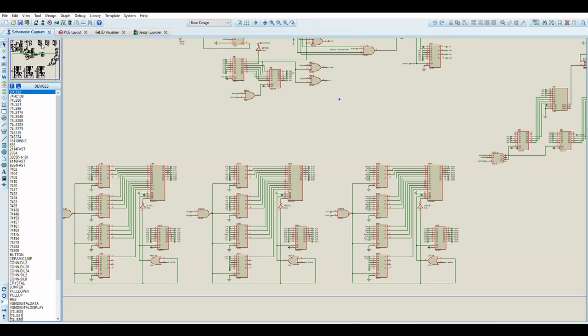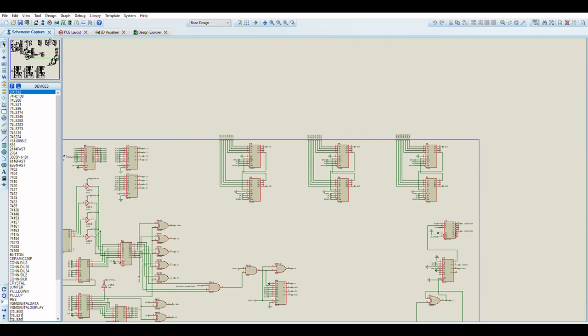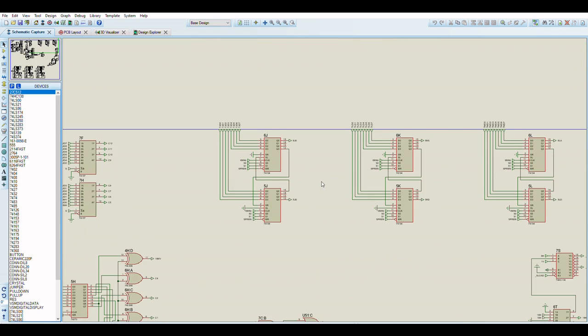So what it does is that the whole timing of this is very carefully timed so that the read for the next 8 pixel chunk of the sprites starts at exactly the correct position where it can start feeding into these 3 clocked shifters. Okay, so these 3 shifters will define how the sprite is horizontally shifted.